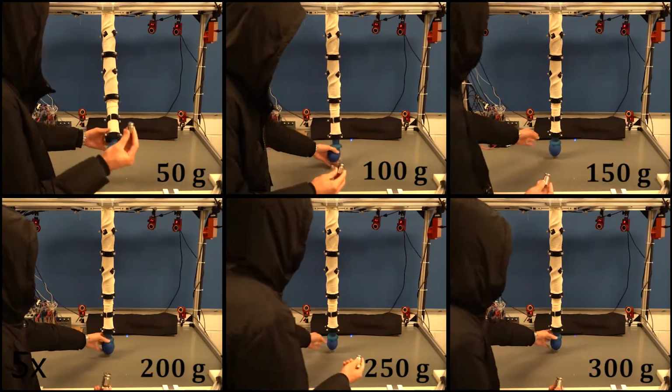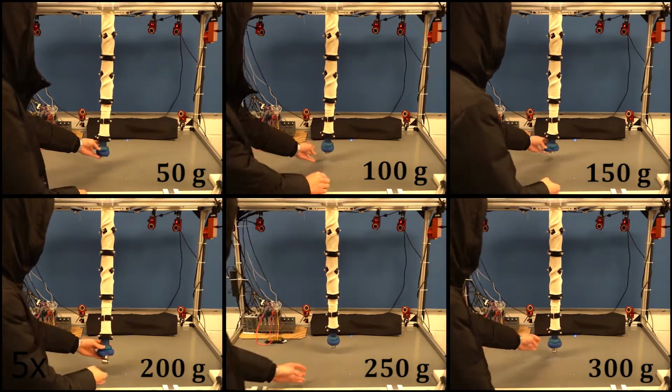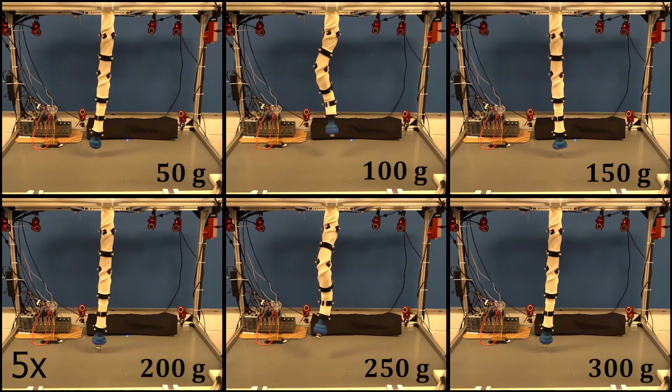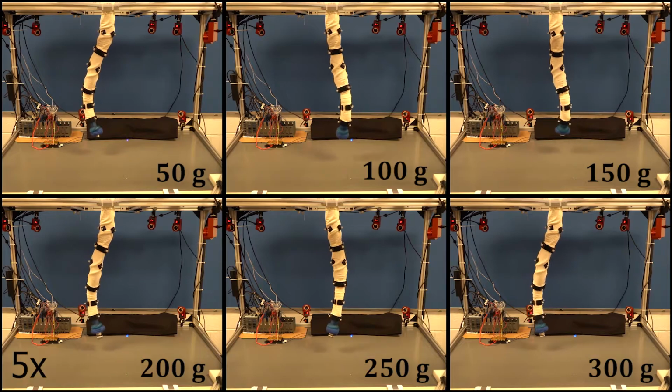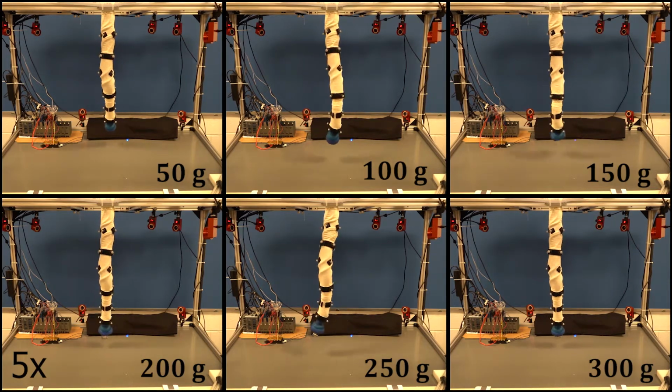To do this, we begin by measuring the response of the system under random control inputs for a variety of different payloads. We then use that data to identify a matrix approximation of the Koopman operator, which provides a linear description of the dynamic behavior of the system under various loads.